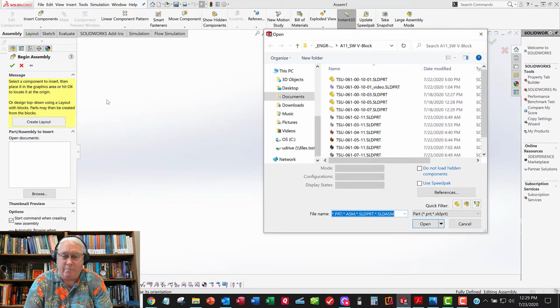If you want to change something in the part, you got to go to the part model, open it up, and then change it there, and that change will ripple back up to the assembly model. And similarly, when you go to the top level from the assembly model, which is the assembly drawing, if you update this part model, it updates the assembly model, and then it also updates the assembly drawing. And so this is the whole idea behind parametric CAD modeling. You don't have, like, an AutoCAD drawing where you got all those lines and things, and you got to move everything around independently. You change one thing, it updates another. That's the meaning of parametric.